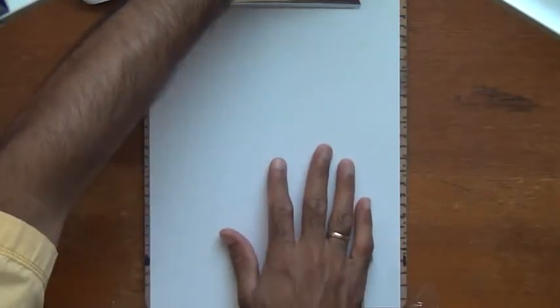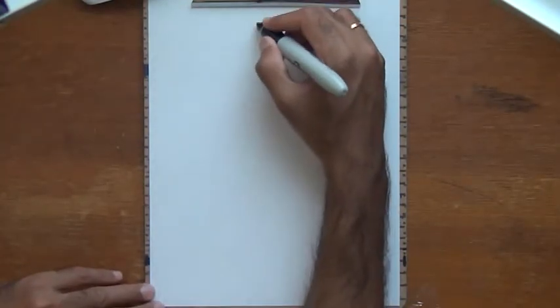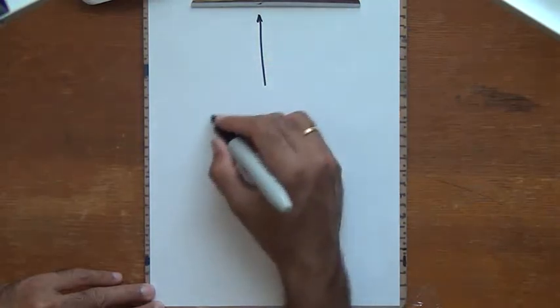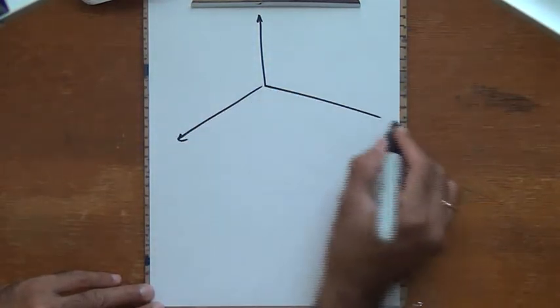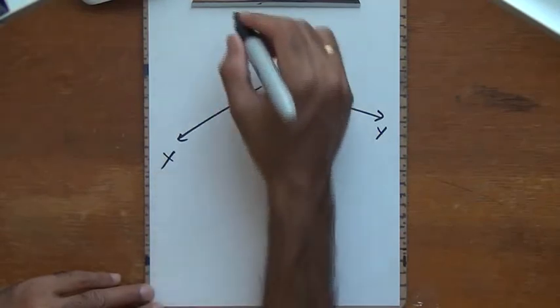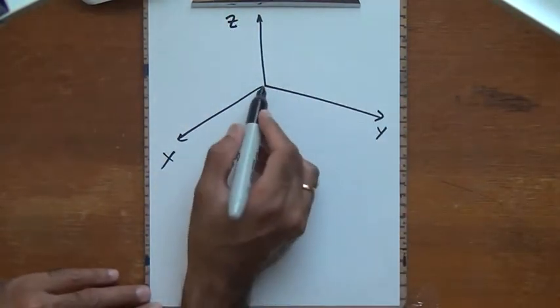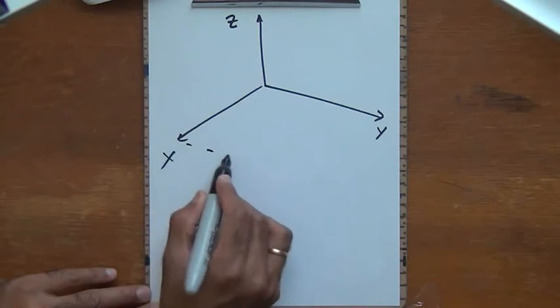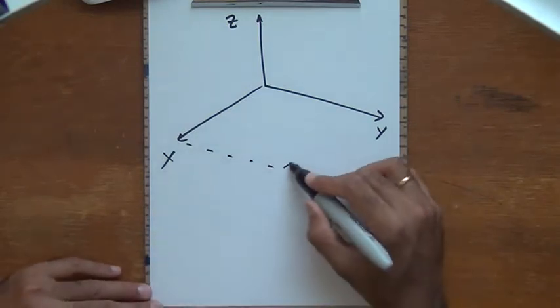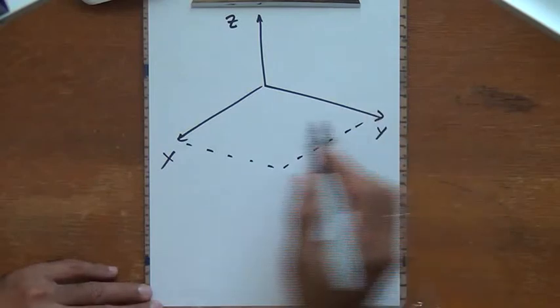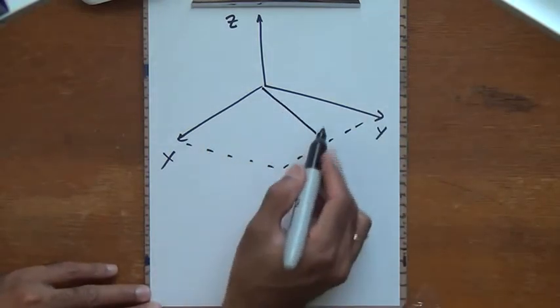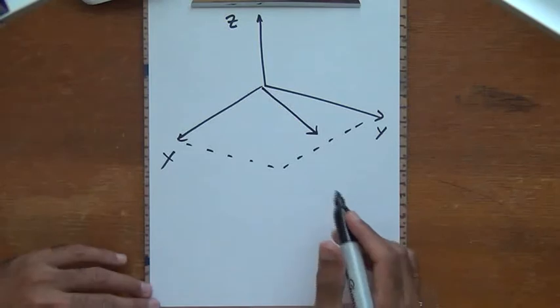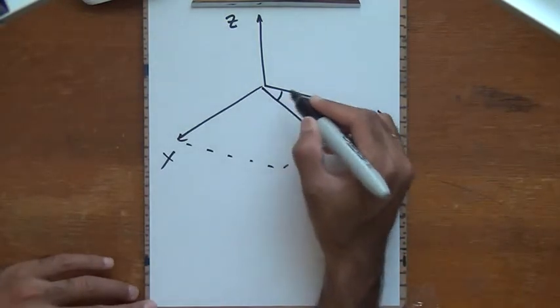Alright, so in terms of taking the F3xy component and splitting that into components along the x and the y axes, I redraw the picture slightly. This is the z, the x, and the y direction, and I know that on this particular plane, the xy plane, the angle that I'm given for the force vector F3xy is 30 degrees with respect to the y-axis.